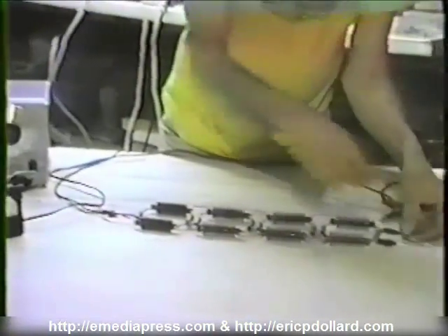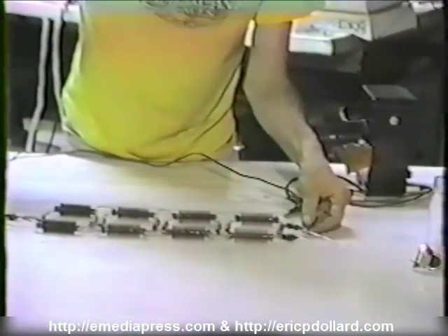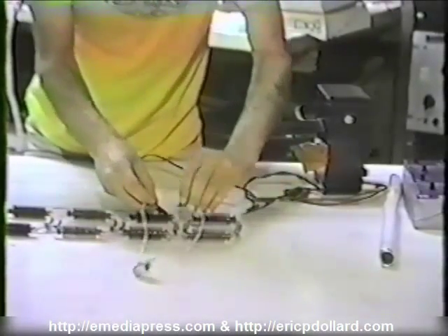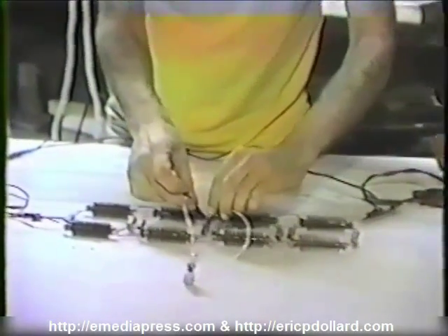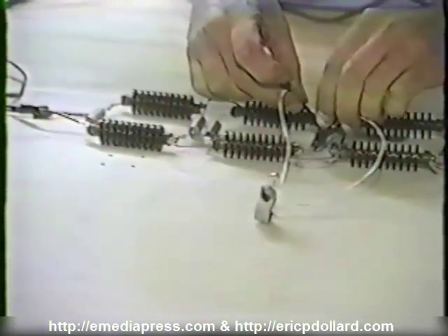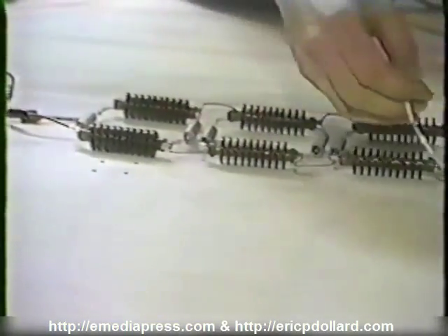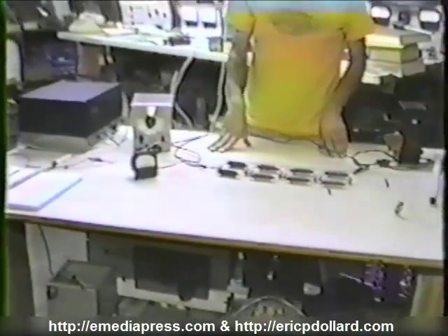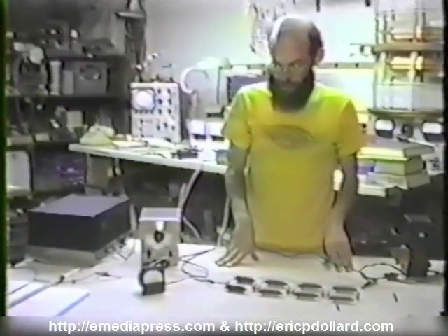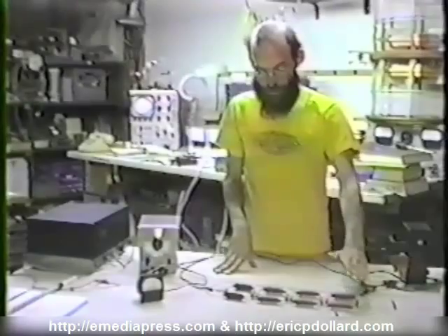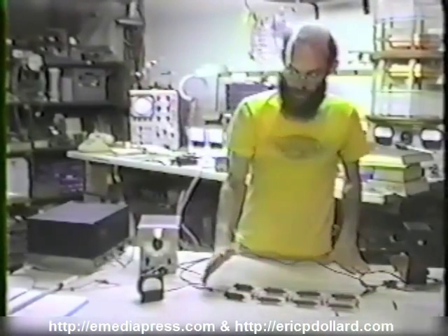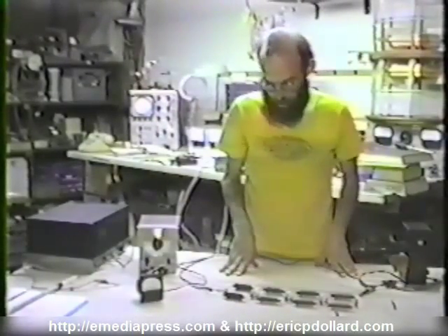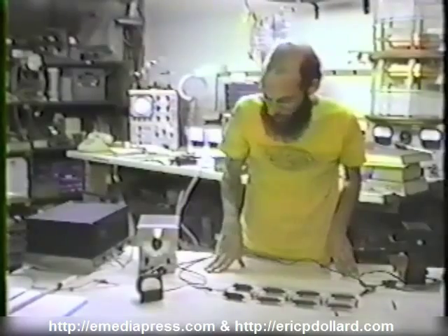Now with the dielectricity, we can start from the end, bring the bulb off of overload a little bit, and we can probe down to the next stage. It's a little weaker, and here it's not even measurable anymore. So the dielectricity has dropped off going this way, and the magnetism has gone this way. So we can see our classical distribution of magnetism and dielectricity on a TEM line, where the magnetism rises towards the low impedance source, and the dielectricity rises towards the open circuit or high impedance load end of the line. Of course, no load being hooked up at this point.